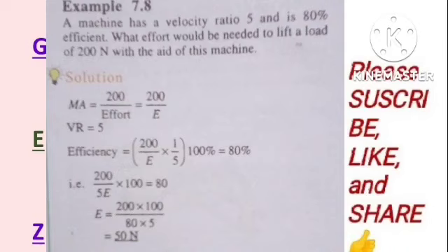What effort will be needed to lift a load of 200 newtons with the aid of this machine? Now in this case, we are told that the velocity ratio is 5, and then we have the efficiency as 80%. We also have the load. All we need to look for is the effort.